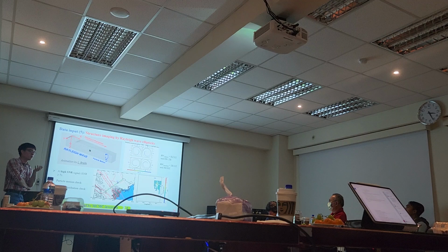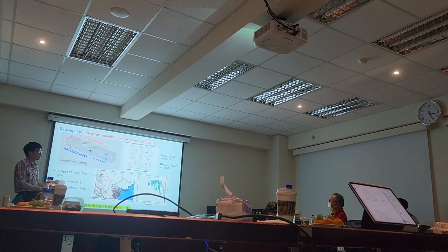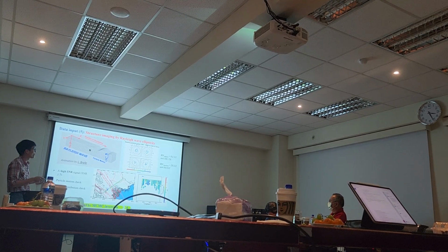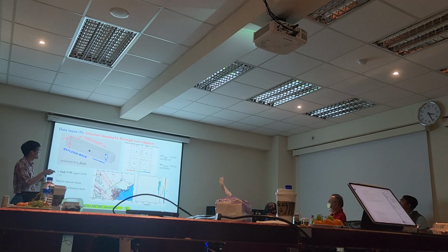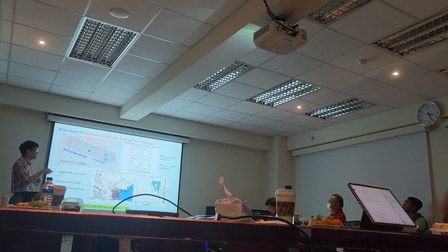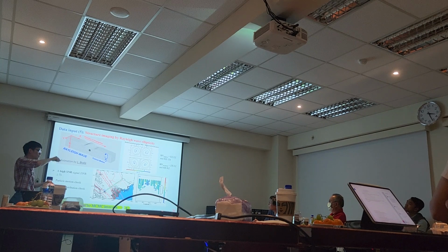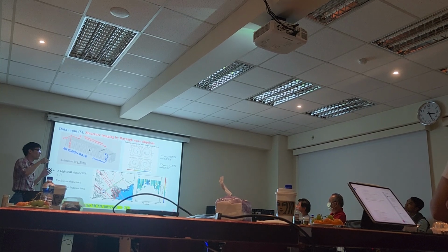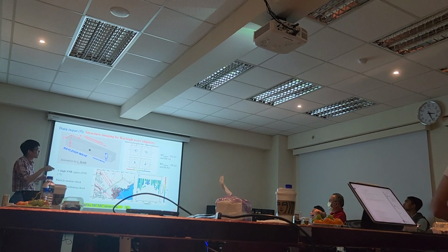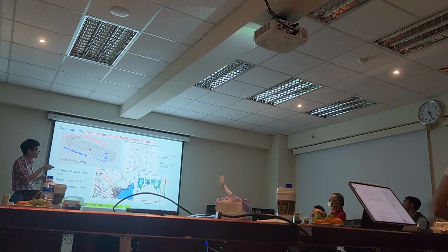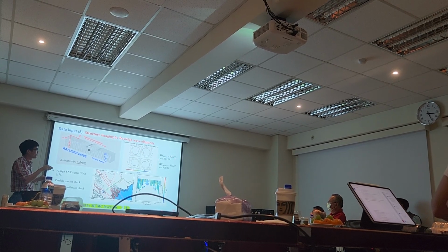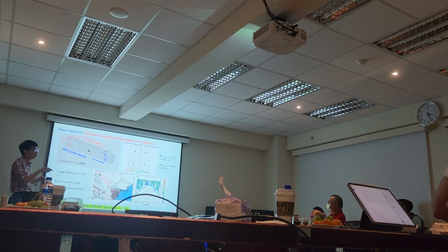Another kind of data we can extract from cross correlation is the Rayleigh wave ellipticity. The Rayleigh ellipticity is the ratio between the horizontal and vertical directions. We can obtain this by calculating the ratio of the ZR over ZZ component, combined with the RZ component for the other station.